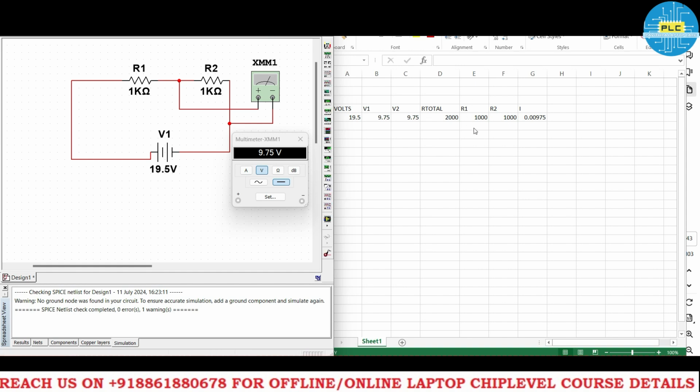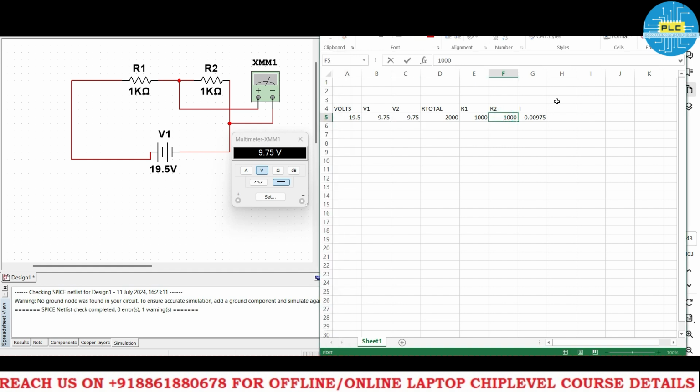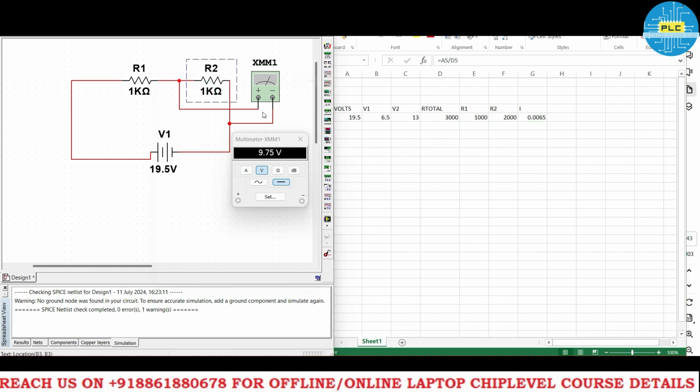Okay, in case R2 is greater than R1, what will be the result? See, I will make it 2K. I made it 2K. See, the current is less. It was 9 point something, right? So 9 something was there. Here the total resistance is 3000 and the voltage across V2 is greater than V1. V1 was 9.75 but it reduced. Okay, practically we will check in case R2 is 2K.